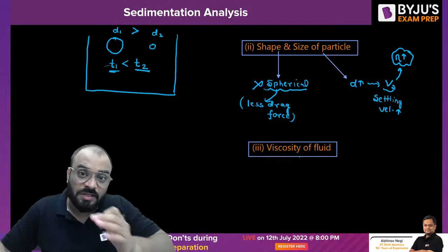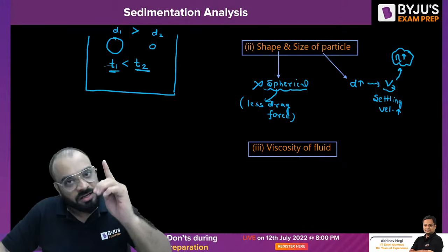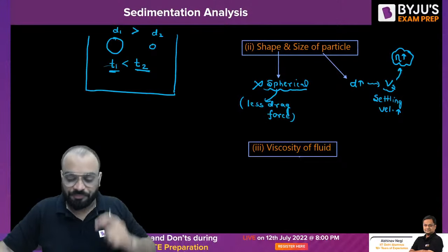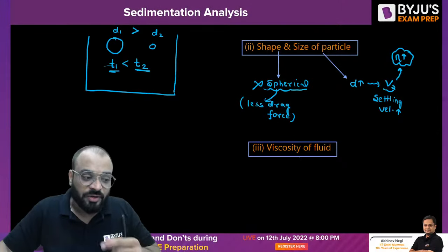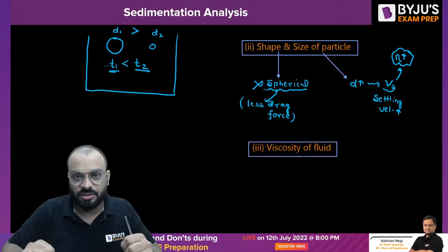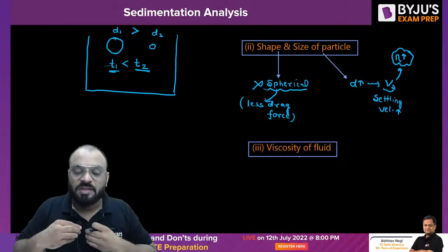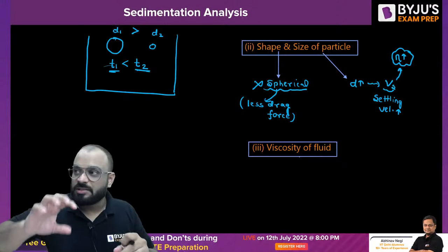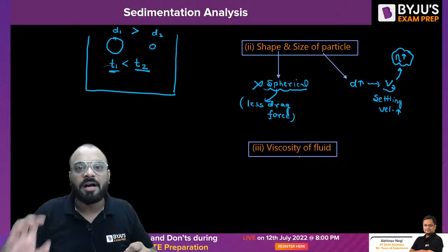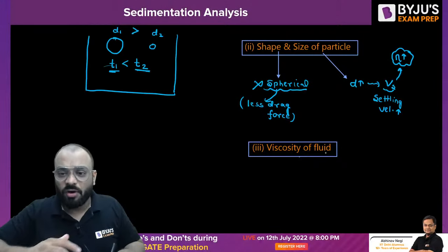But if we talk about size of particle, we can control the size of particle by using coagulation. Do you know that there is a treatment process in your water treatment plant known as coagulation? Coagulation is the process by which we add a coagulant into the water so that it can react with the alkalinity and give us some gelatinous PPT. Right?